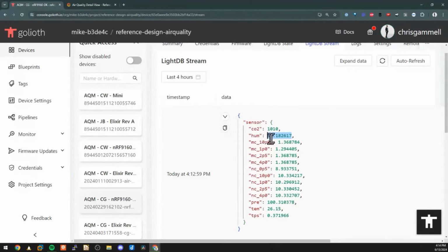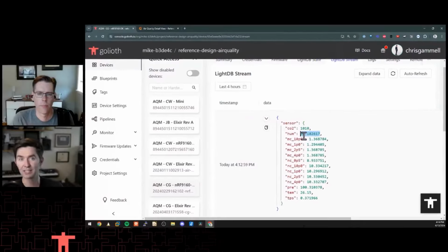And then finally, particulate monitoring. That's often 2.5 micron and 10 micron, so it's the size of the particulate. It's actually the SPS30 from Sensirion. It's basically an intake fan with laser lights showing you how big the particulates are that are going through there. So say I was a smoker and I was smoking right now, you would see different size particulates going through the fan, and you'd be able to tell that sort of thing. It's probably not measuring smokers, though. You'd want to use this in a pollution context, if you live near a busy road or things like that.